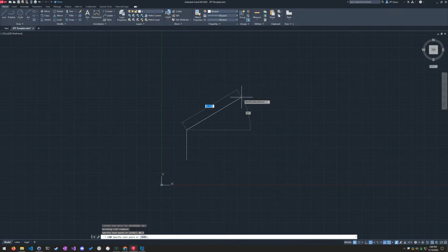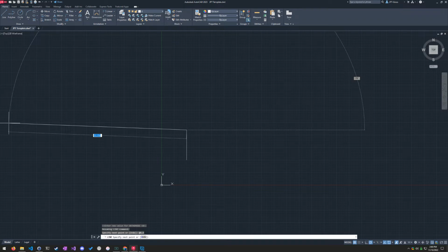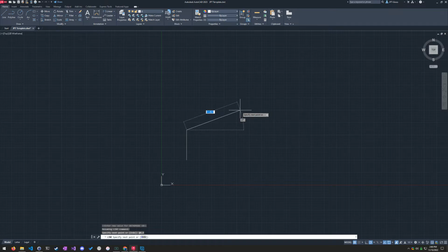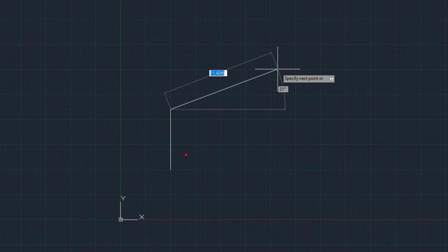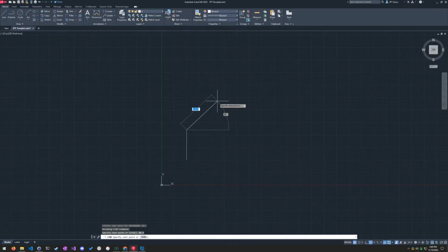And it didn't do that angle. The reason why is because of that symbol that I put in, which means what we did from there was we said the 0 means we don't want to go left or right at all, but we will go up 6 units, or 6 inches in this case. And now we can do the same thing. If I do @ 15, 0, and then press enter, that was the same thing.